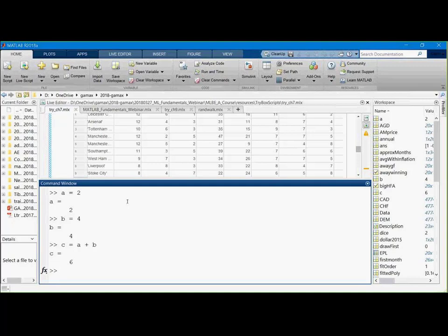At this point, I'd like to highlight a distinctive feature of MATLAB, which is its ability to deal with matrices natively. So for example, if I redefine the A variable as a 3x3 unity matrix, and if I make the B variable a 3x3 magic square, now A and B are both 3x3 matrices. If I want to multiply these two matrices, I can use the same syntax as before, just instead of plus, I use the multiplication. And MATLAB natively multiplies these two matrices for me.